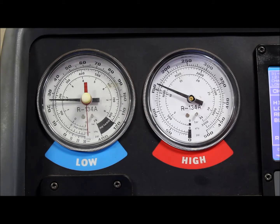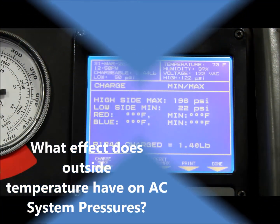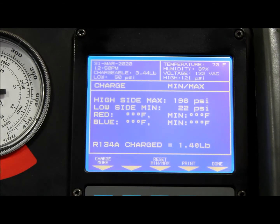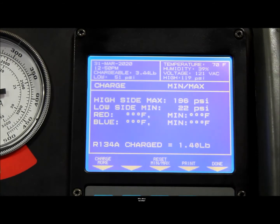So we can now go ahead and do our performance test that we were talking about right at the beginning of this. If you remember, before we attempted it, we looked up some specs and procedures. And two things they wanted you to know before you started this were the ambient temperature, which here is 70 degrees Fahrenheit, and the humidity, which is 39. So we're getting that right off the ACR 2000.